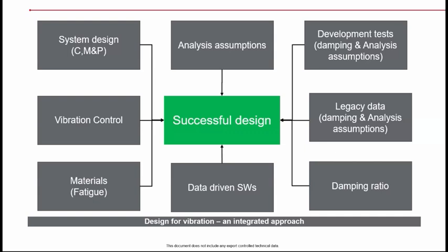I think there is one question from Sridhar in the chat, like how to reduce peak resonance while doing vibration test. I think you answered it, but if you want to take it. While doing the vibration test, we cannot reduce the peak. You can only do that by reducing your excitation levels.